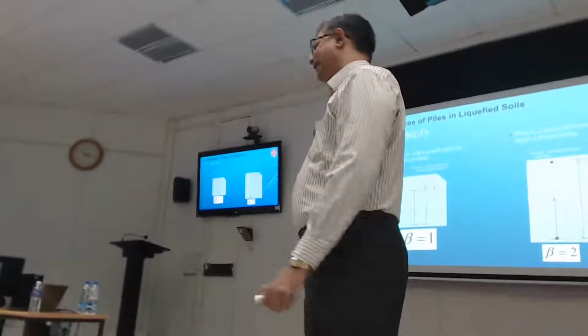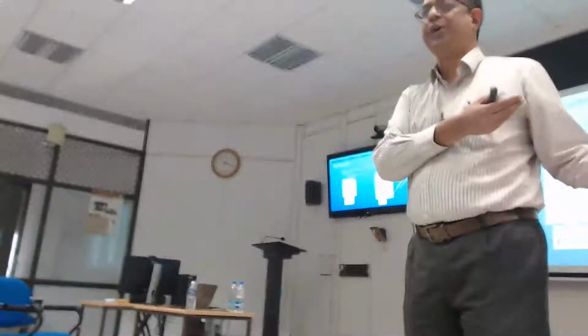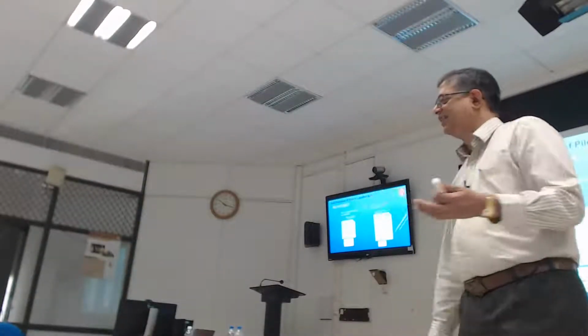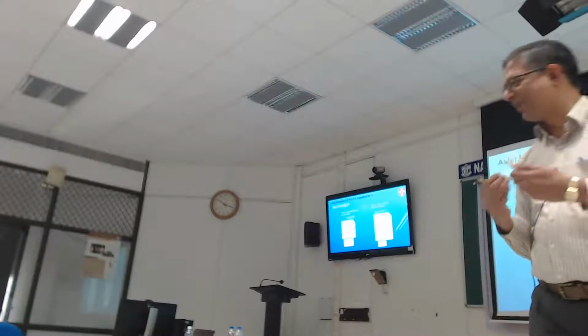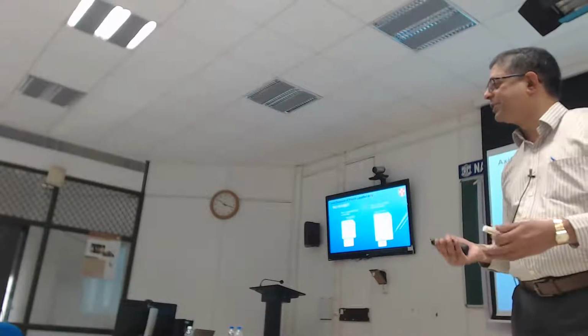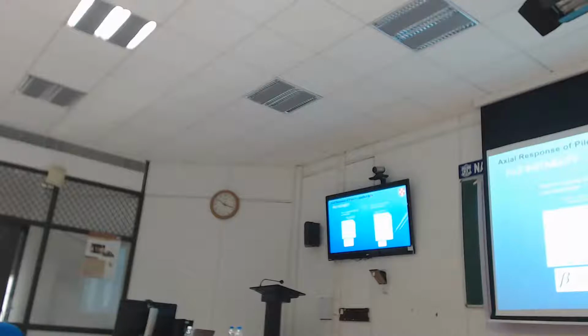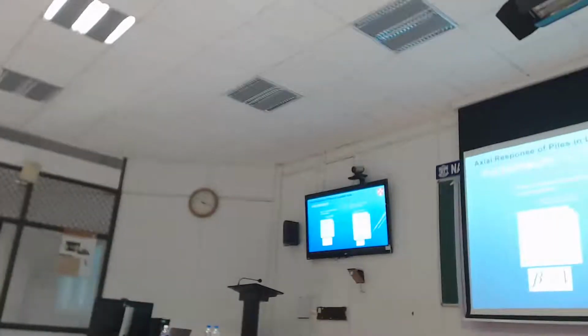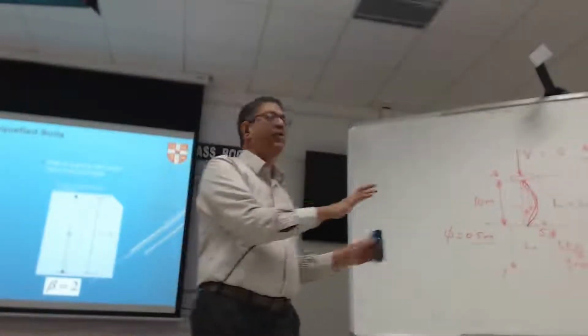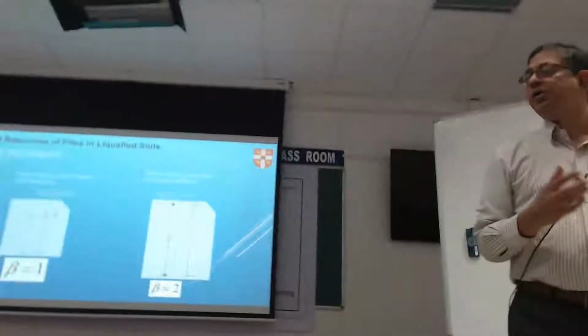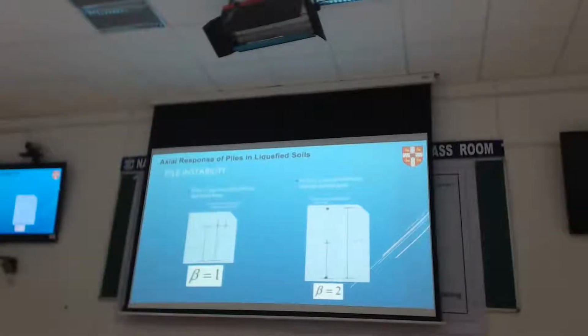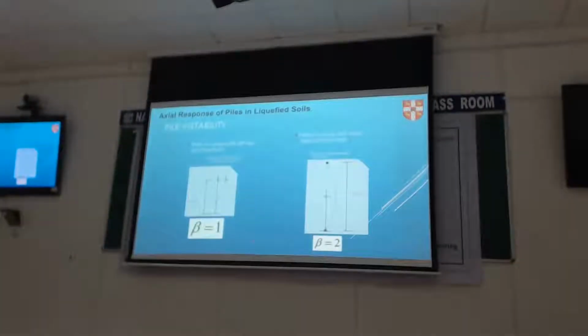What we are not doing here, and that's the research part of this, is what the liquefied soil will do. This calculation is assuming there's no soil. We're taking soil mechanics out of pile design, which is not so good for us, but it's an easy calculation to do. I'll show you how it gets complicated when I add the soil part. Now you understand the background of this buckling. Let's see if it actually happens.